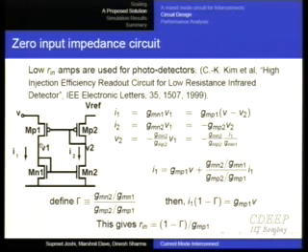So let us say that these two currents are not quite the same, I1 and I2 in the general case. I1 is a fluctuating current, by the way, small case i. It is a small signal i, not the actual milliamps flowing through this, but the deltas. If this is V1, small v is also the fluctuation, delta V. So Gm times delta V should be I1, since all transistors are saturated. So this is the current going through this.